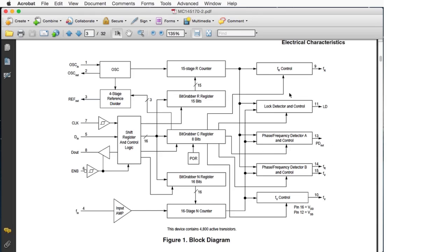So, and the lock detector is also doing a similar thing. It detects if they're out of lock. If those pulses aren't lined up and they're not exactly the same frequency, the lock detector activates and turns off whatever functions on the radio. It might be transmit, it might be receive, it might be the whole thing. Right? Depends on the radio. But that's how that functions. It checks for those pulses being in time. And those pulses, again, are just those frequencies matching. If those frequencies don't match, the pulses don't match.